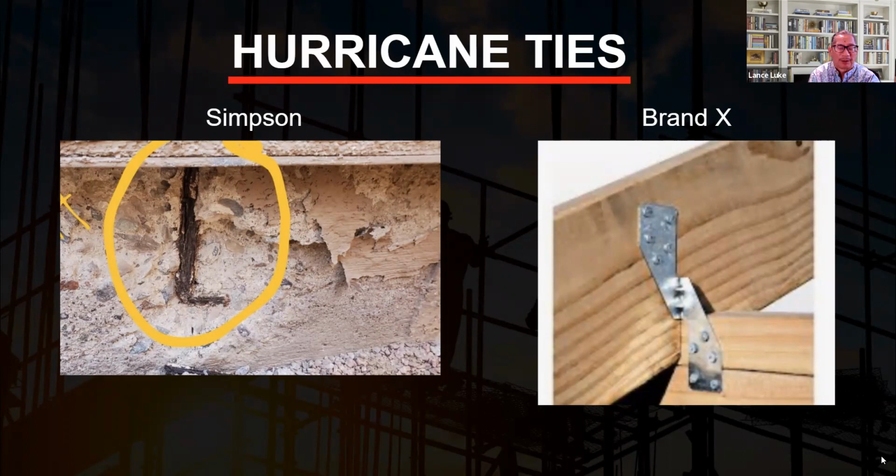So when they pull the form out and you have a concrete slab there, you have these little anchor bolts that are exposed at the top of the slab, okay, and then they make a hole in the wood sill plate that's installed over that little piece of anchor, and then bolted down.